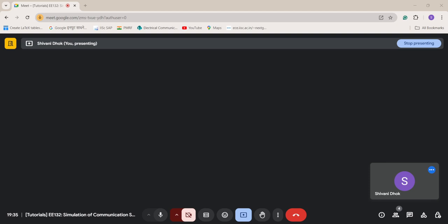Once we run this, what we have is N as 10 raised to 6, M as 4, N naught as 1, then E average as a lot of values, and our constellation matrix as minus 3, minus 1, 1, 3. So this is what we wanted. Minus 4 is minus 4 plus 1, so minus 3, then spaced by 2, and again 3. Okay, so we have reached this point, and now for each of these average energies, we'll transmit the signal.